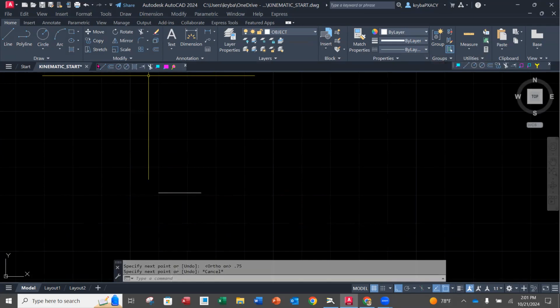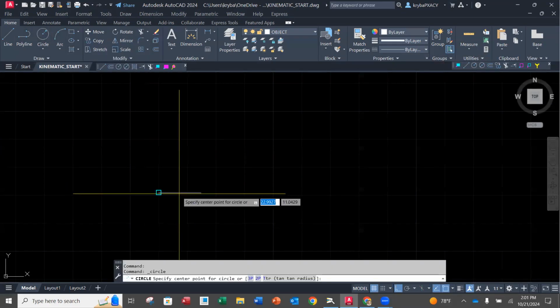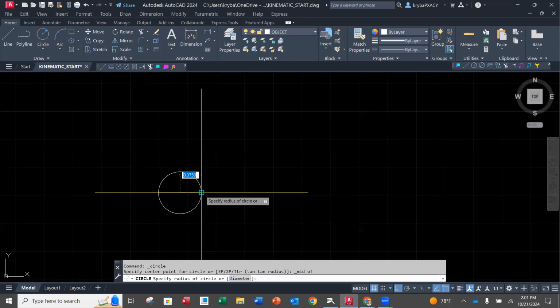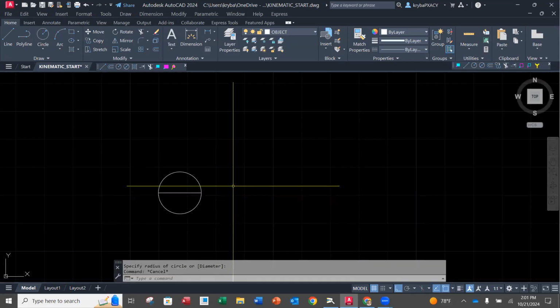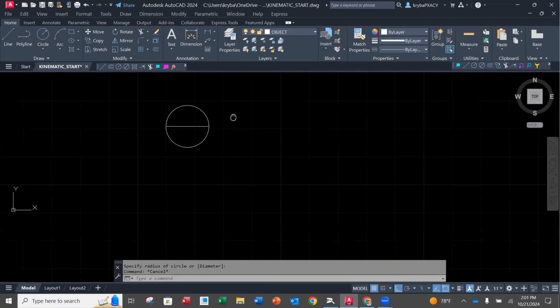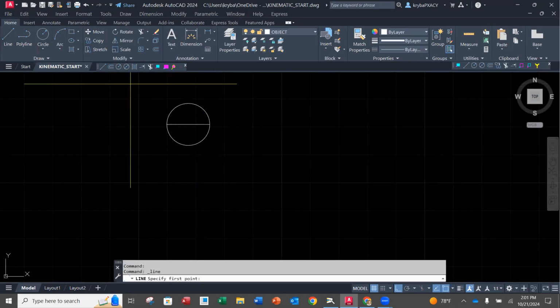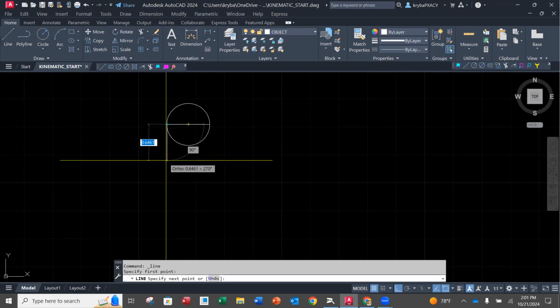And then I'm going to draw a circle so that it's at the middle of that line. So if you need to, shift right mouse button, go to midpoint and just draw a circle to the end there. So that's going to be the top of the arch, if you would, over that frame member. Then we're going to go down, I don't know, about that far.